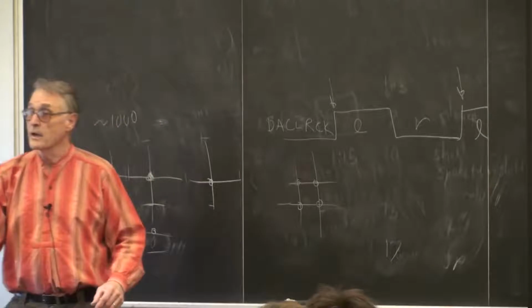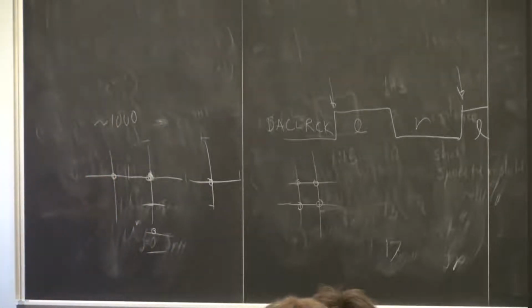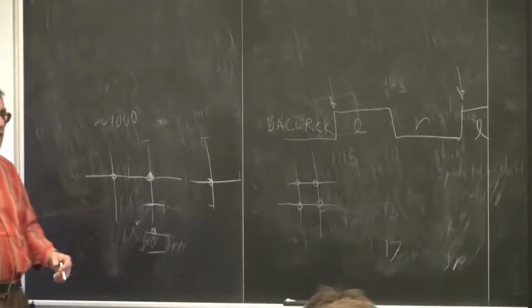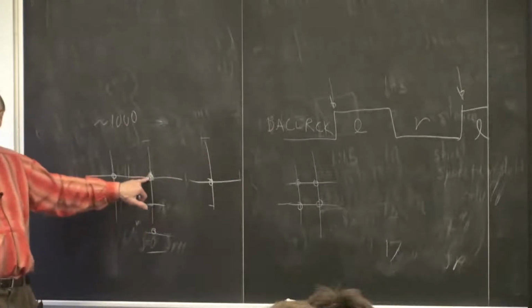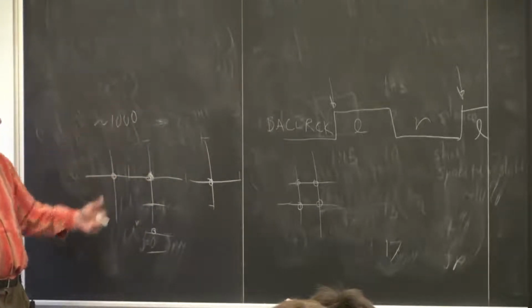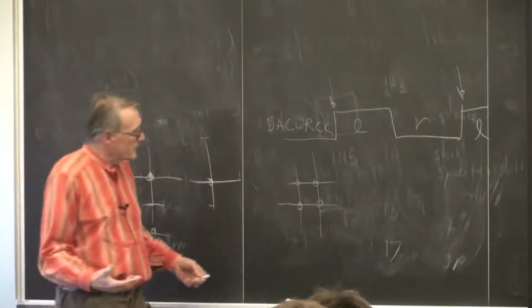And therefore, now you're limited by the number of multipliers on the chip, which it turns out for our chip is 300. You're limited by the number of multipliers to 300, but now you're looking at 300 tiles rather than 300 nodes. All right, well, communication scales well in this case.